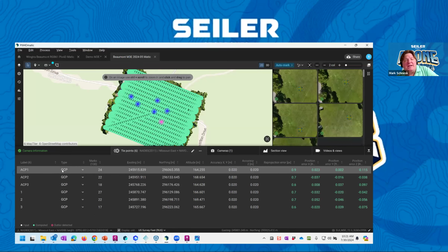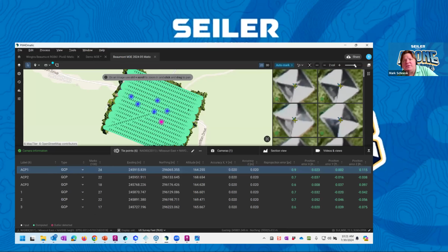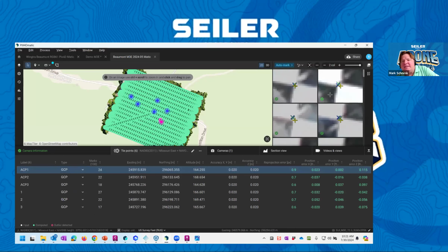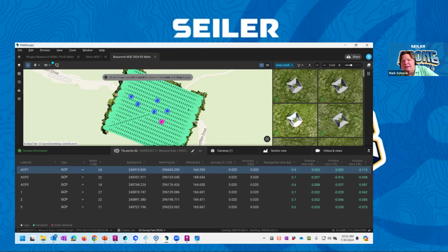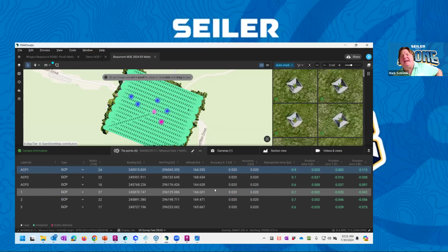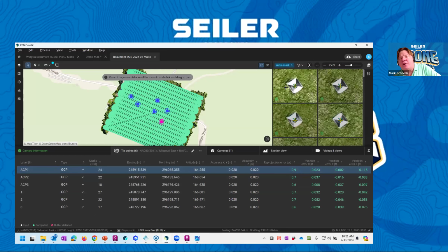Okay, for each of these coordinates, as I look at them, I'm going to mark these in my photo. So here's a typical target. We've applied that accuracy. The blue represents the guessed position. The green is the finished position. The yellow is the mark. As I mark these photos, a lot of software is going to have automatic marking. Some don't. But basically, with an RTK or post process, they should be pretty darn close. We're just nudging it that last 2 or 3 feet.